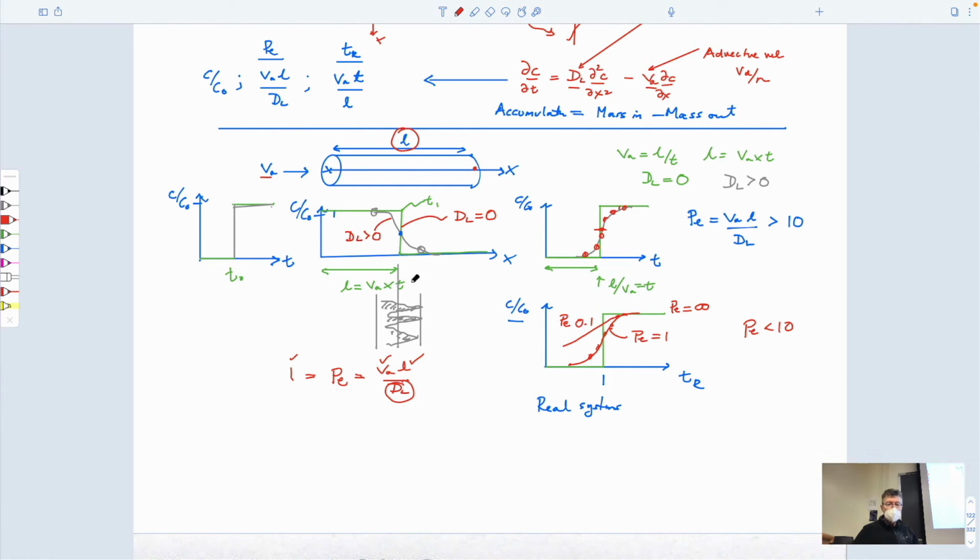And so this dispersion, this whole behavior, is a function of this kind of mixing with fast highways and very slow highways for transport. If you take a core out of an aquifer, which might be a small portion of this, you don't get that structure embodied within the core, and so you don't get this behavior embodied within the experiment that you do. So doing your experiments in a core that you take to the laboratory, if you're looking at advective flows at relatively high Peclet numbers, they won't give you the right amount of dispersion. They'll always underestimate the amount of dispersion, and so they're not very useful.